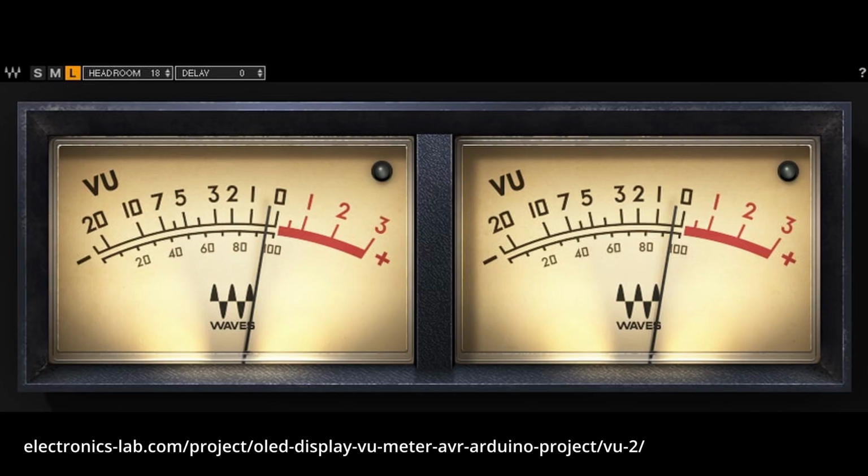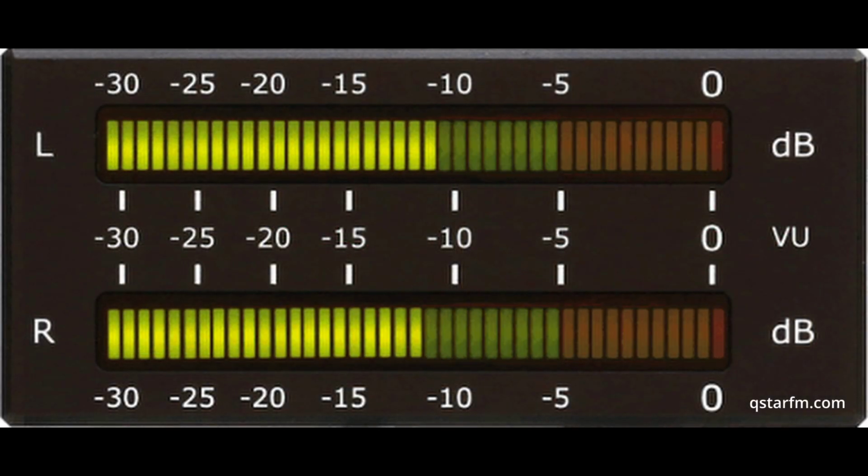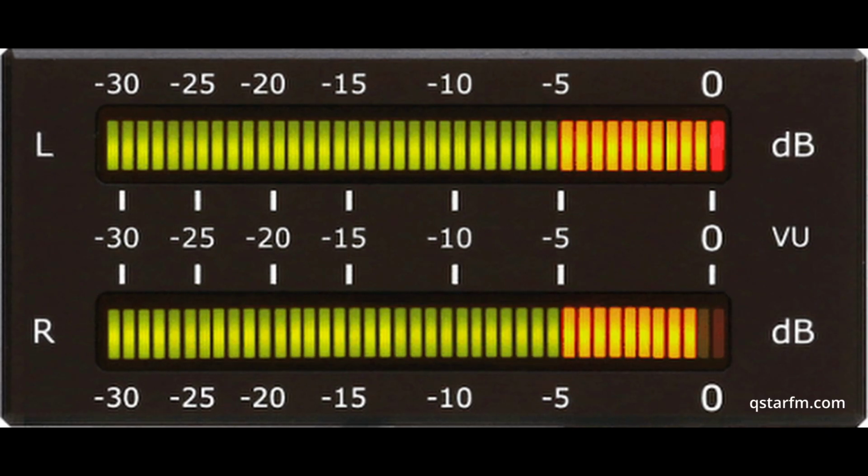And these were designed such that 0 dB was your saturation level. So your needles were over to the left, meaning low signal, and as you recorded louder and louder, they would tend to jump up more to the right. So your needles were constantly moving as you recorded. And the idea was to avoid harmonic distortion by going into saturation, which started at 0 dB.